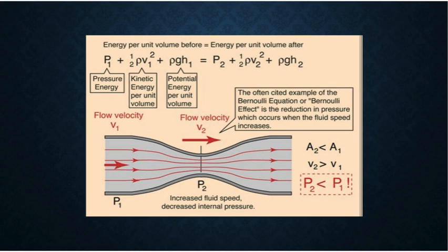Bernoulli's principle is a key concept in fluid dynamics that relates pressure, speed, and height. Bernoulli's principle states that an increase in the speed of a fluid occurs simultaneously with a decrease in static pressure, or the fluid's potential energy. After studying this formula, we can conclude that when the area where the fluid is passing decreases, the velocity automatically increases to conserve the flow rate. Consequently, the pressure decreases. More details will be seen during the upcoming experiment.